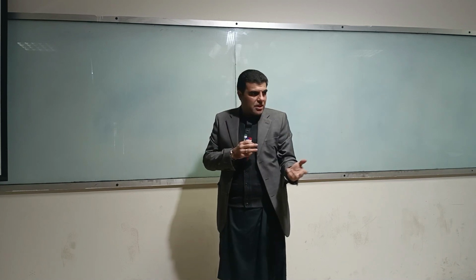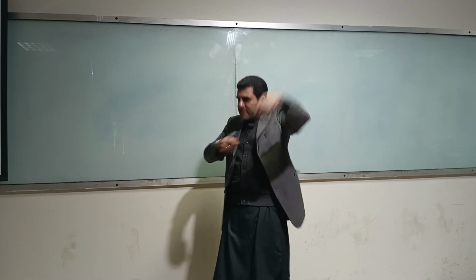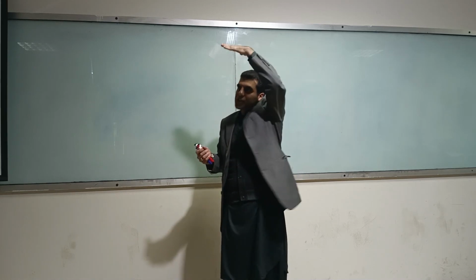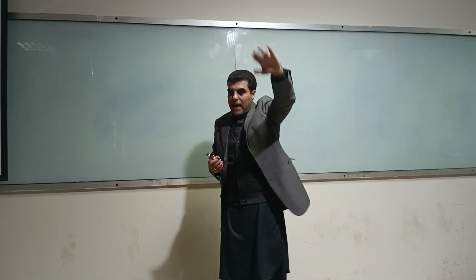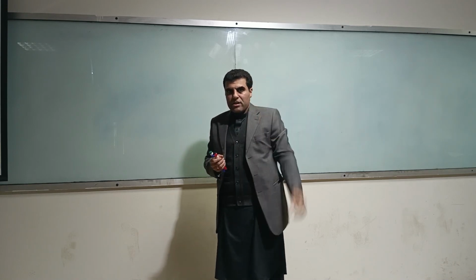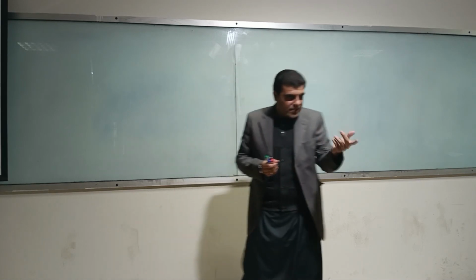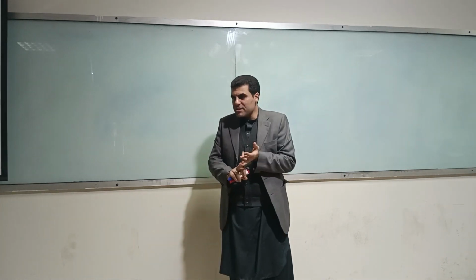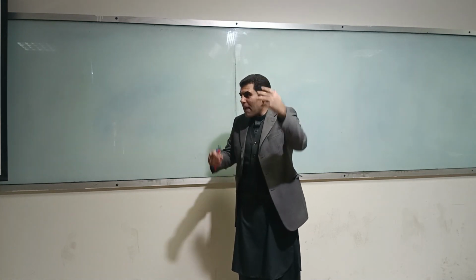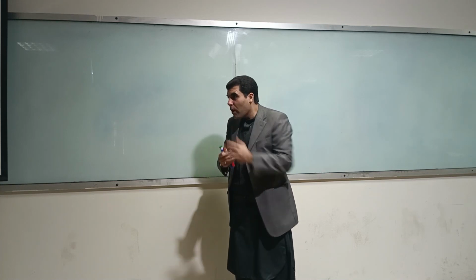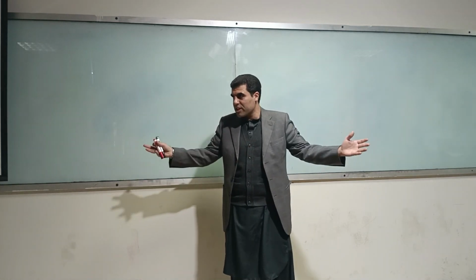In the case of stiffness, I mean excessive deformation, to an extent that you could visually see the slab hanging, like a chain. And number three is stability, which means this overhanging might have overloaded the support structure, and the whole structure would have collapsed.